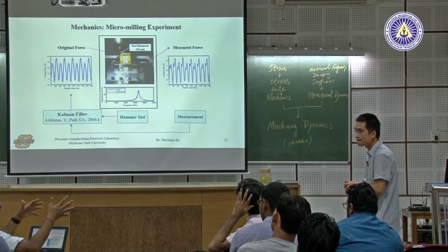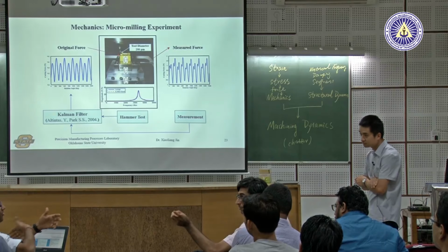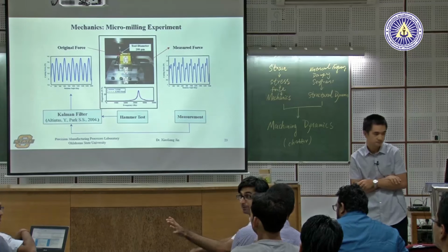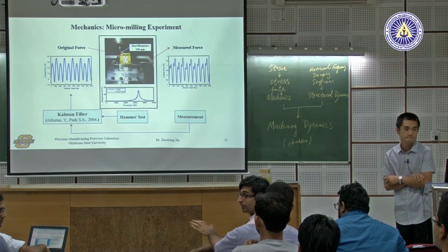Yeah, right. But what do you do for runout in the experimental setup? Because you will have runout. Yeah, live with it. But in your FFT, I think your tooth passing frequency dominates. Which is lucky. In my case, there have been cases where spindle frequency dominates, and what you would see is that one of the passes gets missed. In one half it will cut, in the other half it will not cut because there is more deflection. We saw all this, right? That spindle frequency is dominating, and you just live with it. You can't do anything.